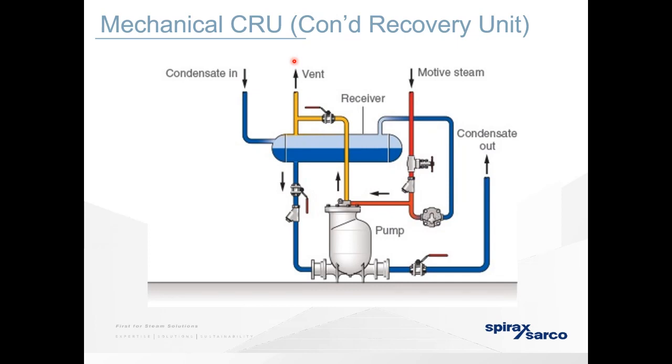If he has a steam flow meter, can he take advantage of that flow meter to calculate the condensate recovery rate in his system? I do believe in that case he also needs condensate flow meters, so that he can see what goes back.